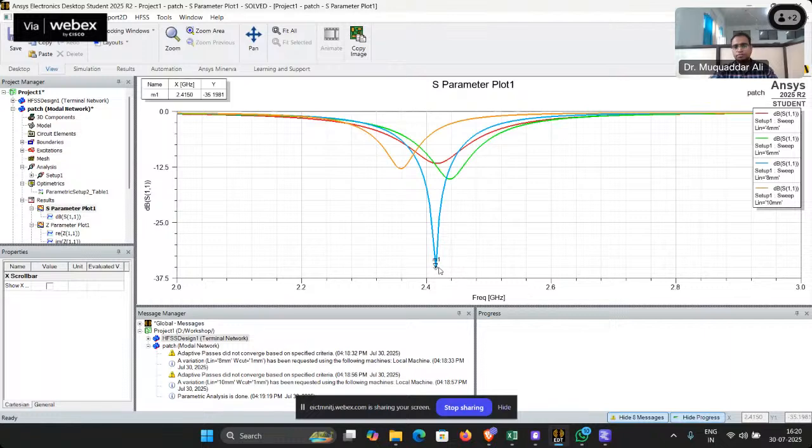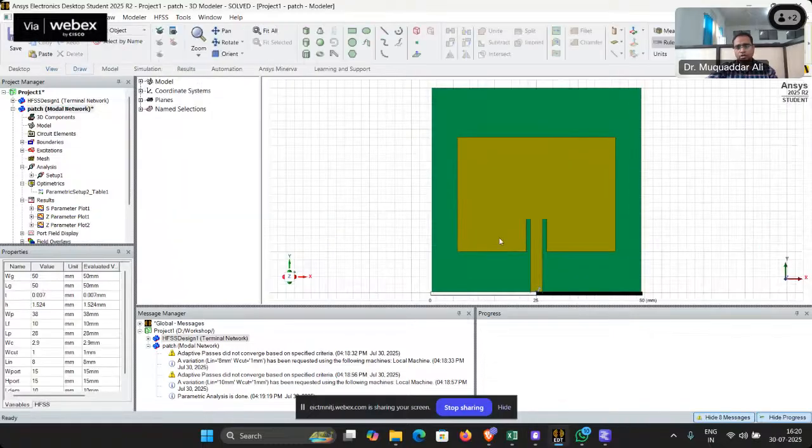At this point, we are getting the impedance matching. So most of us directly see the S parameters, and we see the dip in the S11. So that simply means that our antenna is matching at that point. So sometimes we match this antenna, and by accident we have not properly matched this transmission line to 50 ohm, then what will happen, the propagation effects will take place, and we will be getting different results during our measurements.